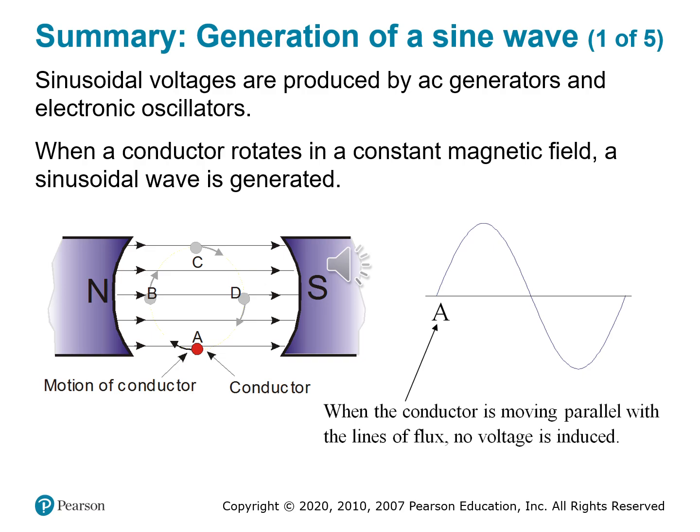At point A, the conductor is moving parallel to the magnetic lines. And what's the result of that, right? We have no voltage since it's parallel. No voltage is induced because there's no cutting action. The key point for this one moment in time is that you have no relative motion across the field lines, so that equals no induced voltage.